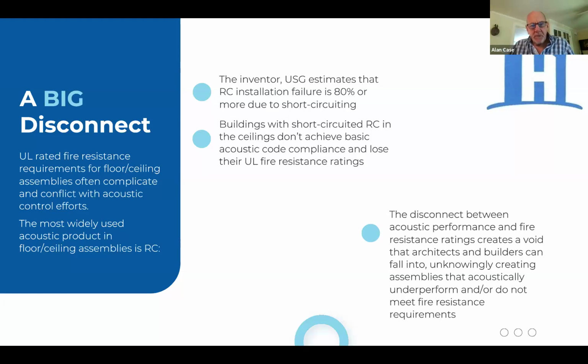What happens is, to obtain a 1 hour fire resistance rating from UL, you have to build your assembly inside one of their furnaces, and it has to withstand an open flame at 1700 degrees for 60 minutes. The metal tends to really respond to the heat, and it warps, and the panels split open, and they've got issues.